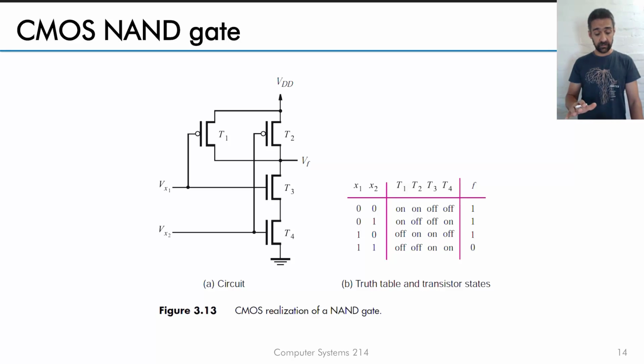So here's the NAND gate. As you'll recall previously, the NAND gate had these two transistors, and they are in series because they both need to conduct to pull this point to 0. Now just think in your mind, we had the resistor here, but now we want to put a complementary pair of transistors here.